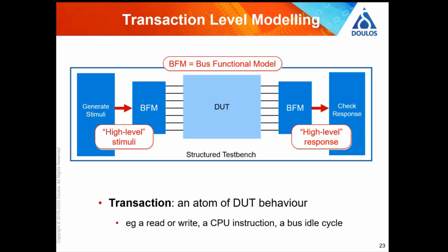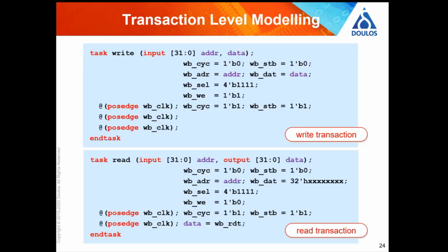And as we'll see shortly, it's much better to check a transaction. It's much easier quite often to check a transaction than to manually check the raw outputs of the DUT. So let's implement a basic transaction-based test bench. And as I've just said, we're going to use tasks.